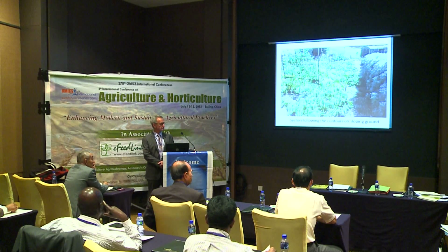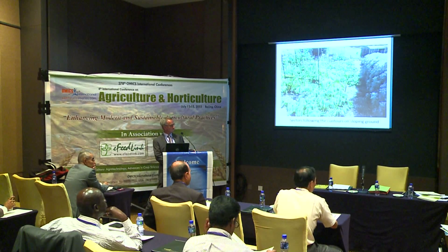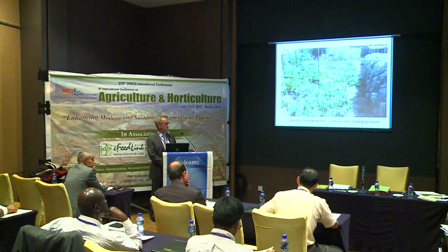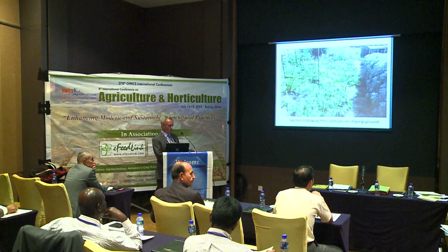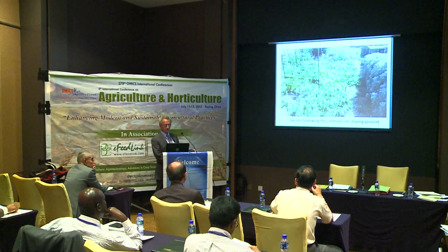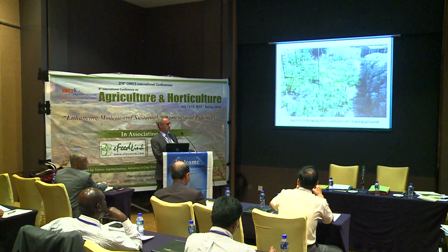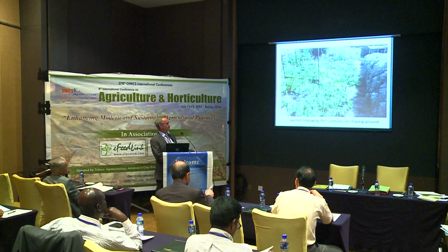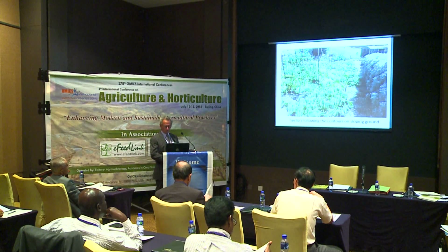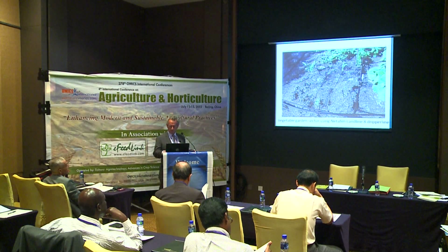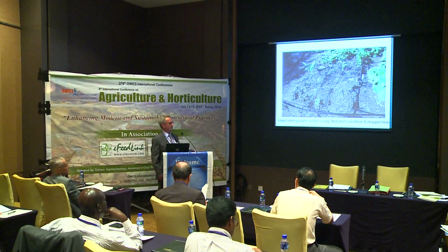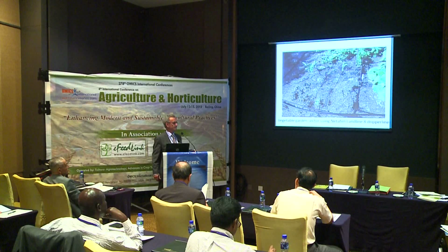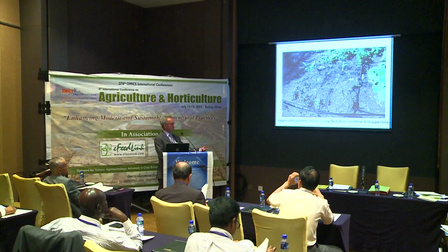Okay, that's an important question. So the likelihood of clogging the nozzles is no higher with measured irrigation. There are a number of different choices for emitters, and for larger applications, I would suggest people use some commercial product like Netafim Landline, which has been on the marketplace for over 10 years, and the nozzles are very resistant to blocking because of the technology that's been developed.